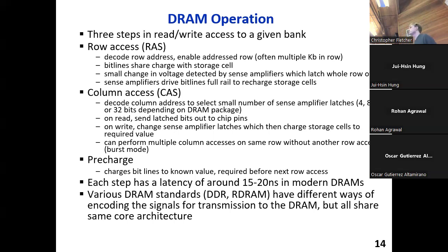Usually you pre-charge to VDD over 2. Does anybody have an idea for why that's a good idea? Pre-charging to VDD over 2, over 0, like the reference voltage, or VDD, the high voltage? Yeah. That's right. That's exactly right.